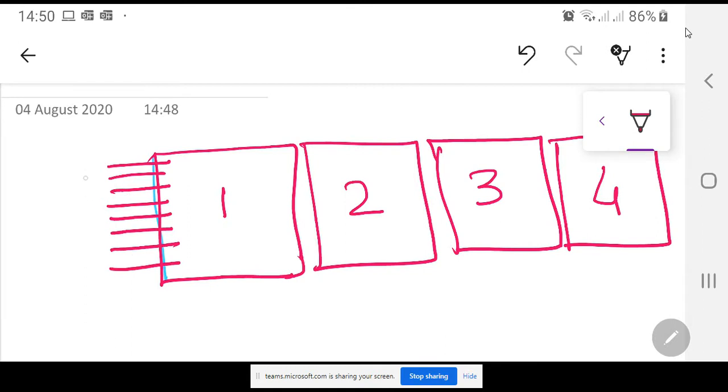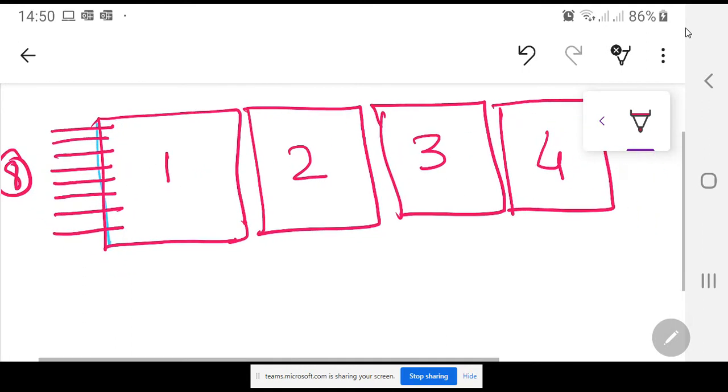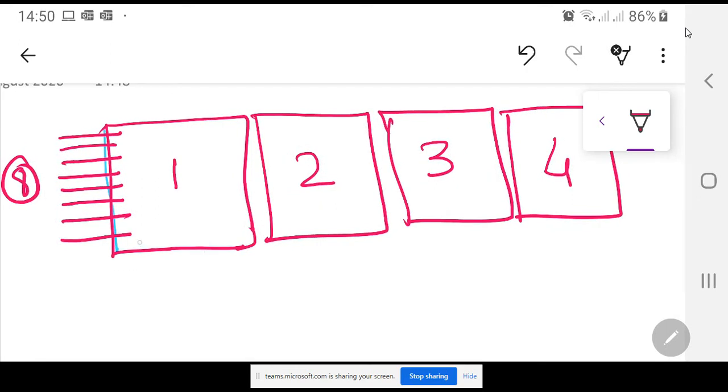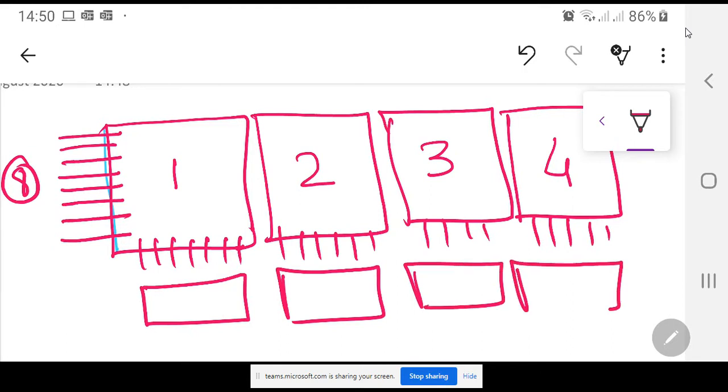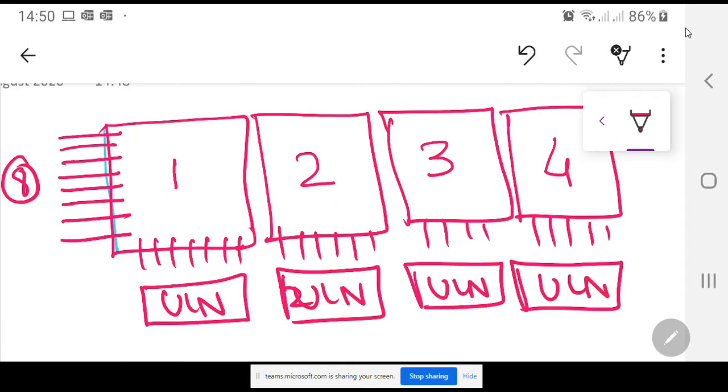So you are going to connect 8 transistor pairs over here, and when you are going to talk about the ULN2803, since here they are arranged in 8 columns like this, 8 columns like this, and 8 columns, for each one of these you are going to have a ULN2803 IC. So this is that ULN IC, this is that ULN IC, this is that ULN IC over here.